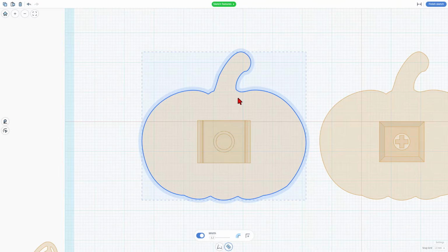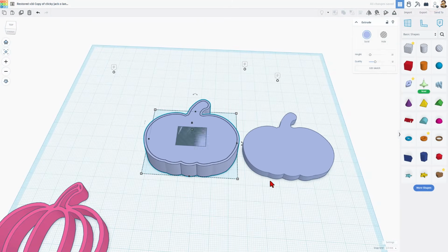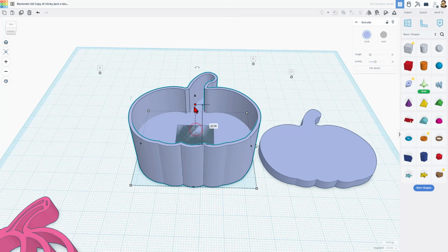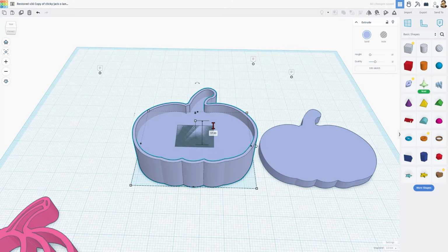Notice all of the old shape, the duplicate, is underneath and will be inside, and this will be the outside shell of our project. If we hit Finish Sketch, now that we've got these awesome walls, we just need to stretch them up. I'm going to tell you the correct number that we want to type in here is 17 and press enter. Now this is a perfect match.